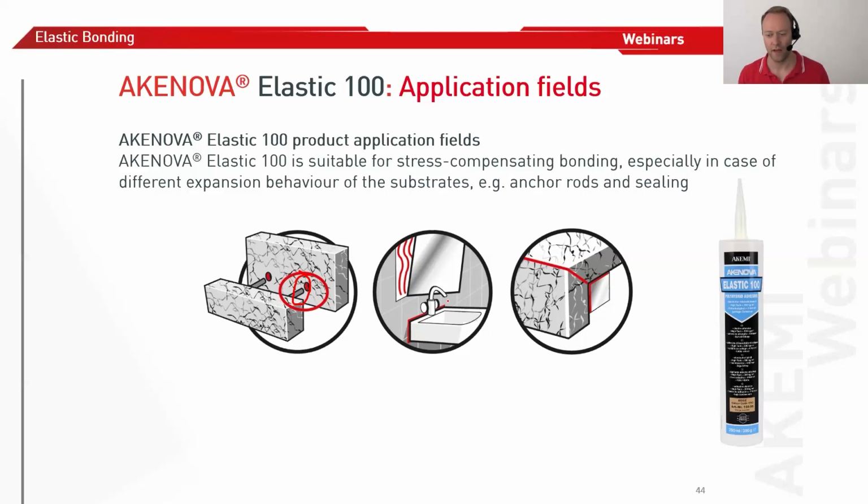And when we look at this picture of the mirror, you can see we put the lines from top to bottom and not horizontally. Why? Because in all areas where you have a lot of humidity, like in bathrooms, a lot of shower air humidity, maybe small water particles in the air, or steam baths, it's better to make the lines from top to bottom when you bond something.